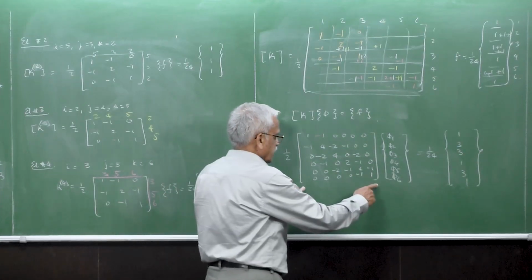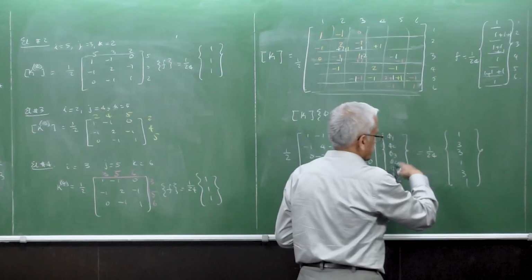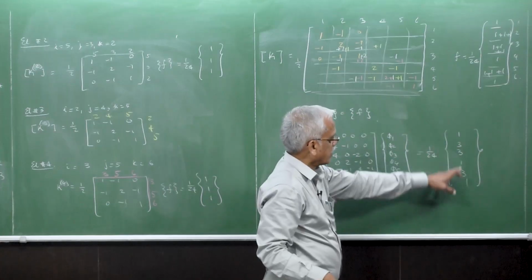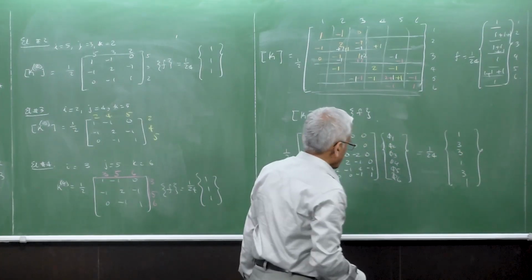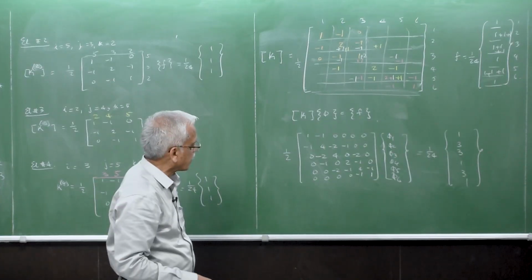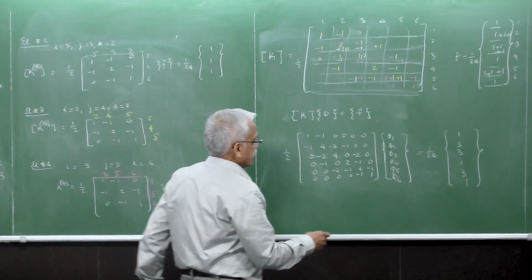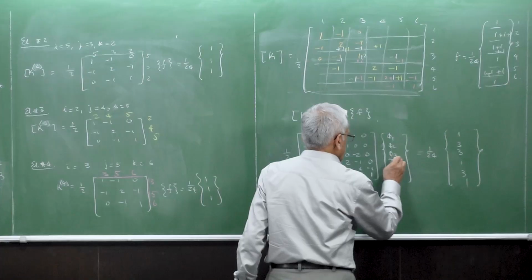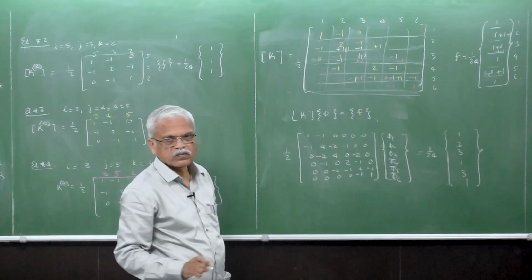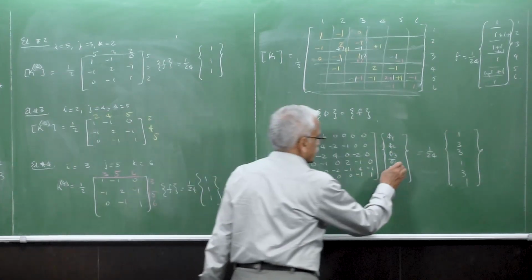And this now is K multiplied by the temperature values at the 6 nodes which are to be solved, and then this is the heat source here. One thing that's been done, as you recall, the boundary conditions are given on nodes 4, 5 and 6. For example, these 4, 5 and 6 have been given to be 0. So now these are simply 0.